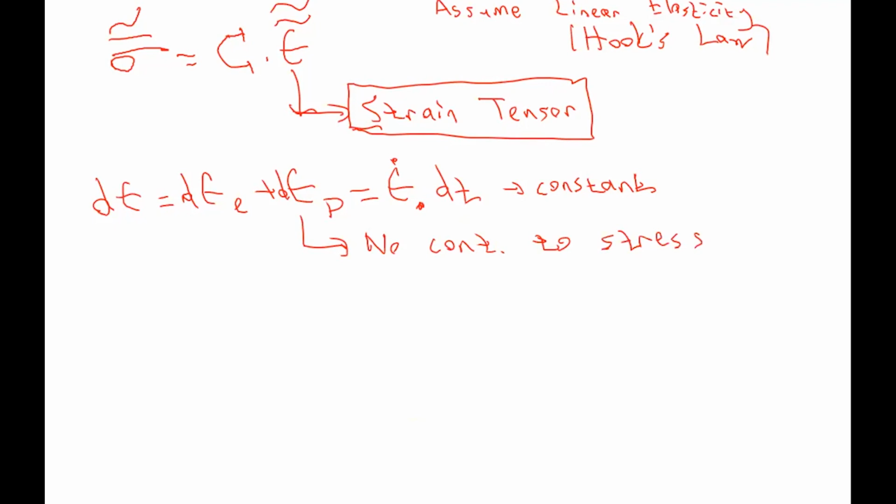In the elastic regime, you only have elastic strain. Then once you multiply it with E, you can calculate sigma. But in the plastic region, we have both elastic and plastic strain. Due to the contribution of plastic strain, the elastic strain decreases, and we see some decrease in the stress-strain response.